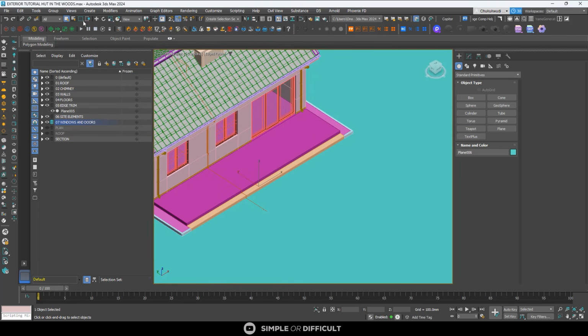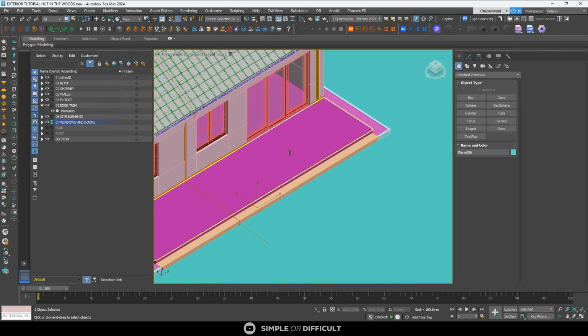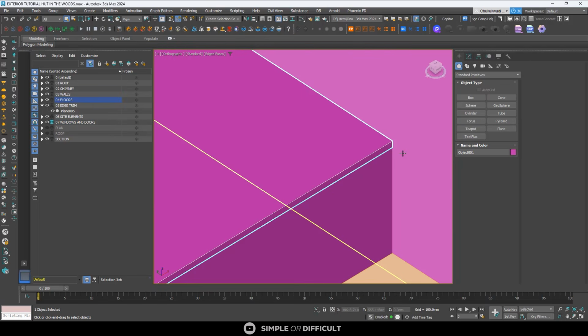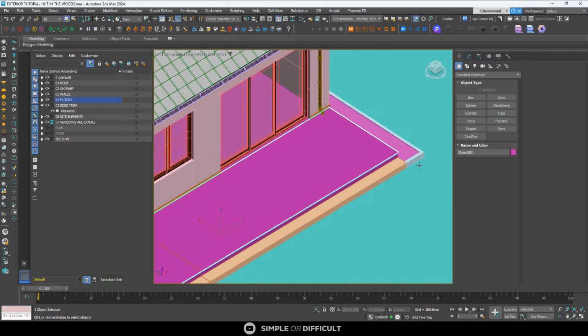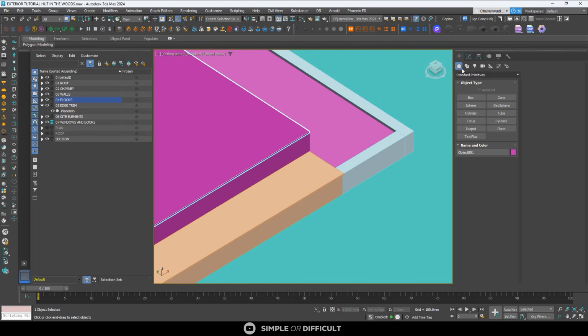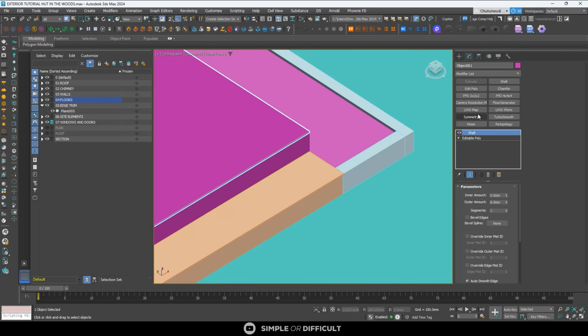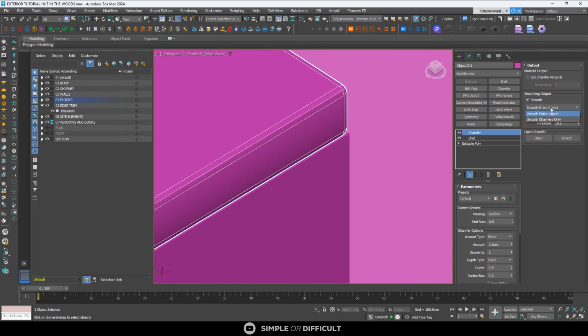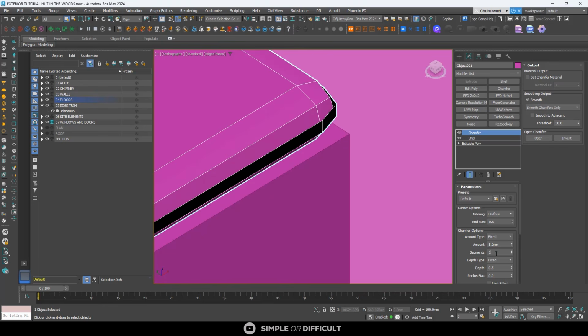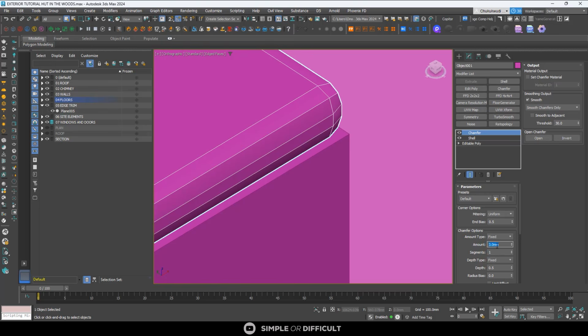Now, last thing but not the least, we're going to add some chamfers around, for realistic purposes. Even though I don't even think it's that necessary, but I want you to have the habit of doing that. So I'm going to chamfer. Make sure it's chamfering. The smooth is just for the chamfer alone. So for here, I'm going to add. This is too small to be having that much. Even 2 is okay for this one.